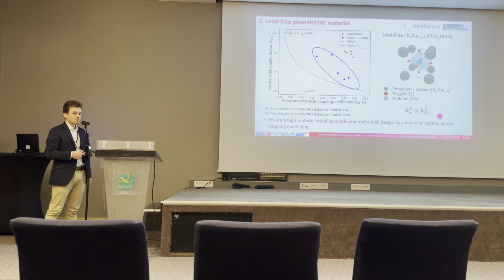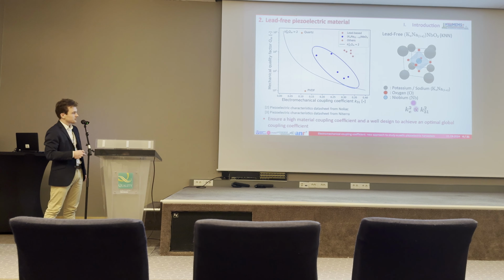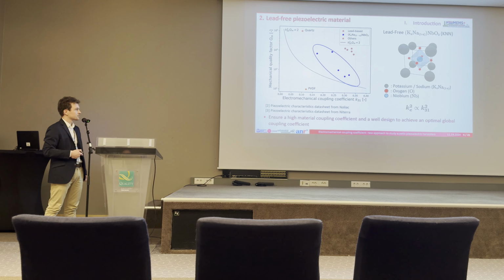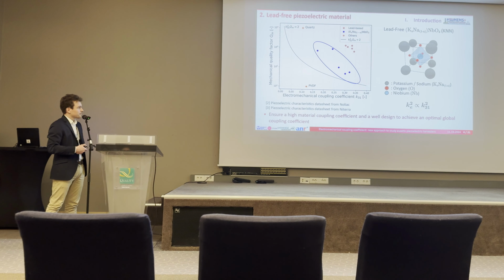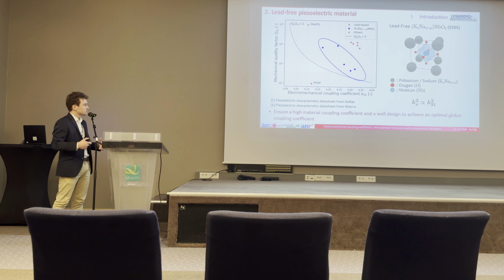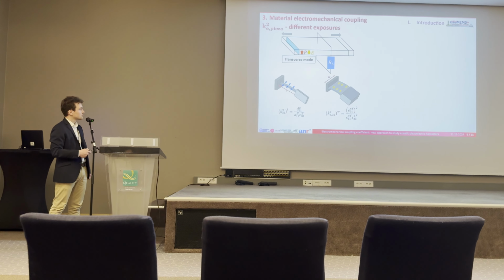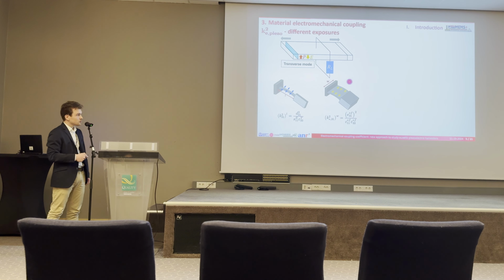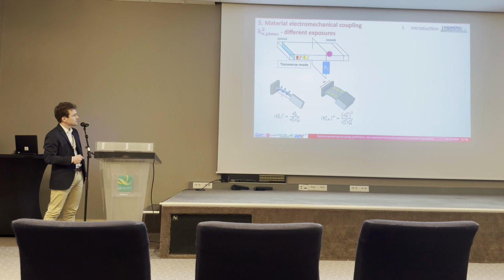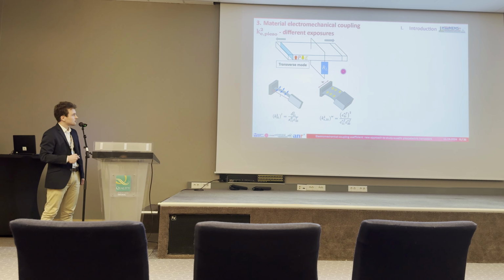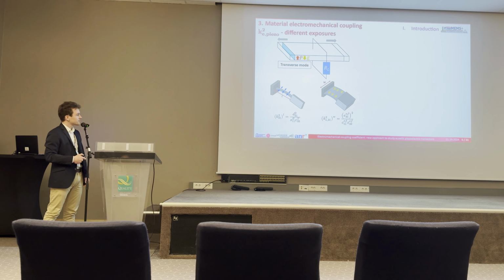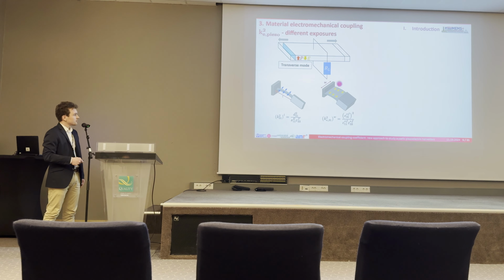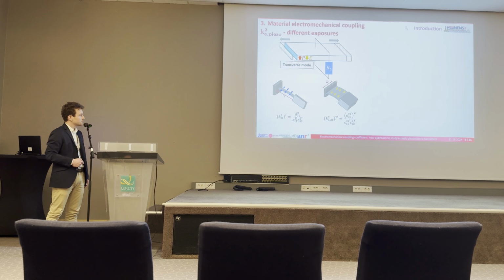We saw earlier the global coupling coefficient, and it is proportional to the material coupling coefficient. So we need to ensure a high material coupling coefficient, and to do this we can have different exposures, which are here. Here you have the transverse mode exposure, which is achieved when the material has a mechanical load perpendicular to the polarization. And for this transverse mode, there are several hypotheses possible. Here is the wide beam hypothesis and the long beam hypothesis.